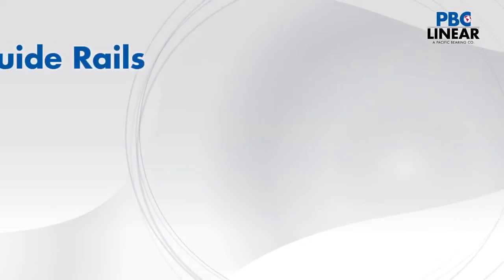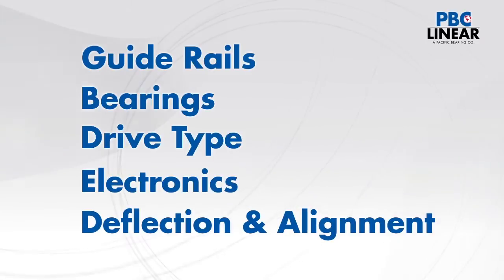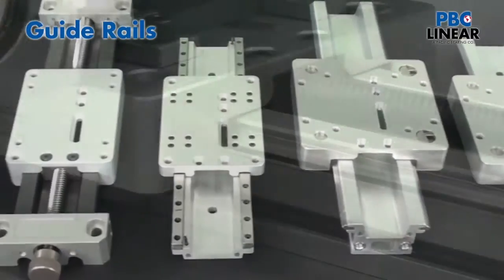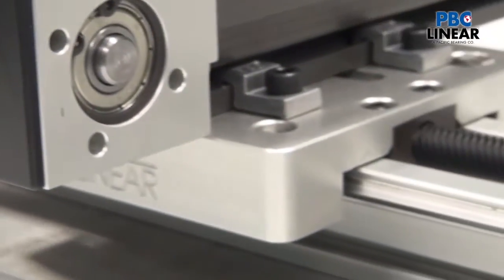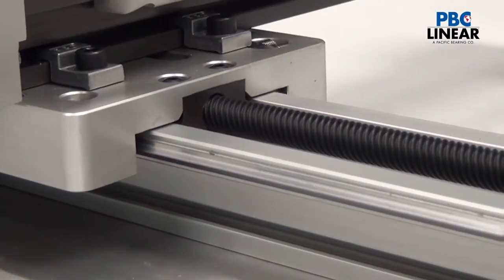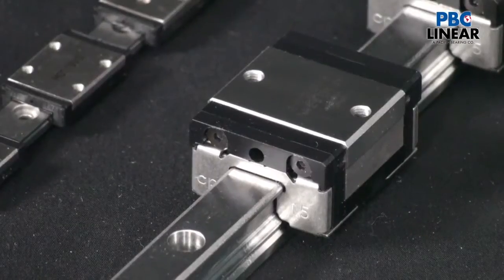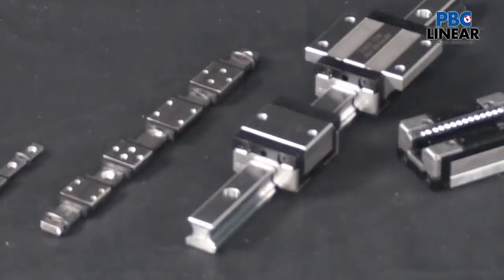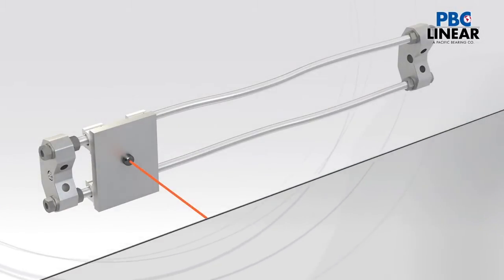So what are the factors that contribute to repeatable and accurate linear motion? First, let's look at the guide rail. A wide array of manufacturers, methods, materials, and specs can result in some misleading conclusions about linear rails. For example, traditional hardened steel shafts or profile guideways are ground to very tight or precise tolerances. This will provide a smooth running surface for the bearing. However, it does not automatically produce accurate, repeatable motion.